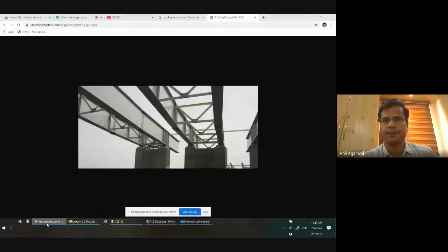Yes, sir. Yeah, so on one pier, for example, you have 2 beams or 2 girders resting, right? And likewise, you can see 2 piers here. So on each pier, you can see 2 girders resting, and then the 2 girders together are connected with some bracing system, right? Now, if you notice it carefully, these are not beams; these are bracing systems which have vertical dimensions, a vertical truss, and these are also equally effective, right?